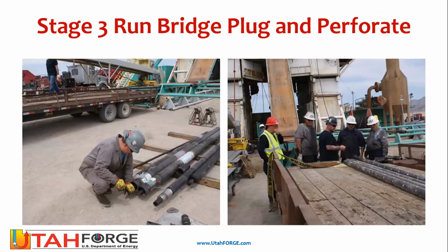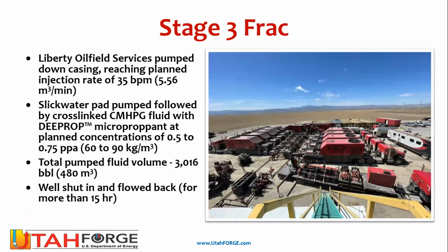And we moved on to running a bridge plug and perforating for the third stage. The third stage was similar to the second stage at about 35 barrels a minute. I don't see the exact volume of fluid pumped here, but it was about 2,500 barrels that were pumped at rates up to 35 barrels a minute.